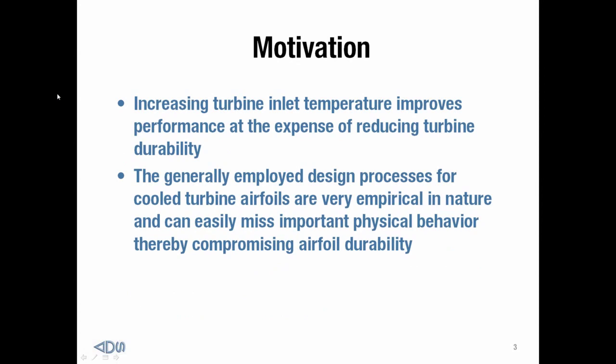Now, the way these cooling systems are generally designed, it's done through empirical processes that are based off of experimental data. And they've worked fairly well, but as we try and push the temperatures higher and higher, that gives less and less margin for error. Very small changes in metal temperature can cause very large changes in the lifespan of the parts.